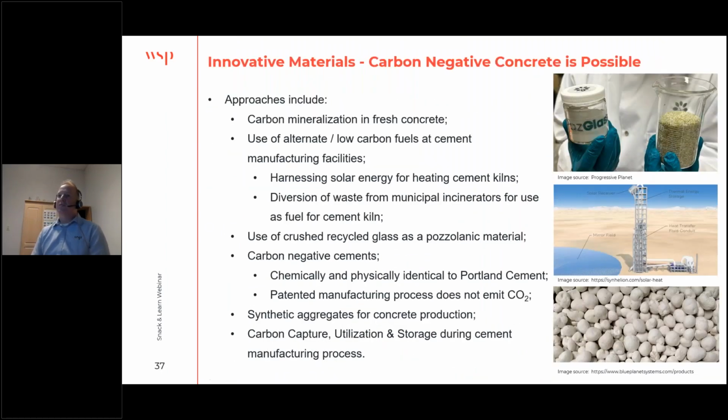Future approaches may include carbon mineralization in concrete. We've even seen a cement kiln in Mexico that now harnesses solar energy by using a mirror field and concentrating that heat into the cement kiln. Recently, we've seen the use of crushed recycled glass as a pozzolanic material, and that should be becoming code approved in the very near future, if not already. And even some carbon negative cements that are chemically and physically identical to Portland cement. There's a patented manufacturing process that does not emit CO2, and it's the hope that that can become more mainstream and commercially viable in the not too distant future.